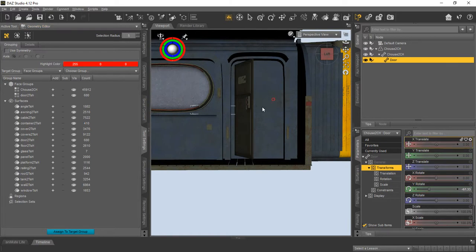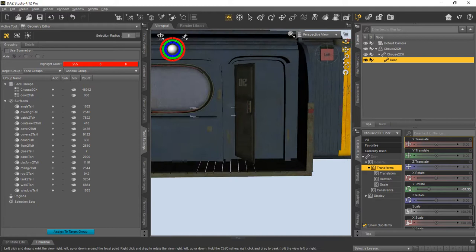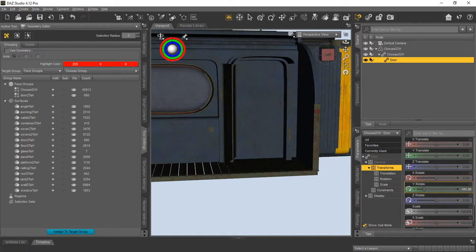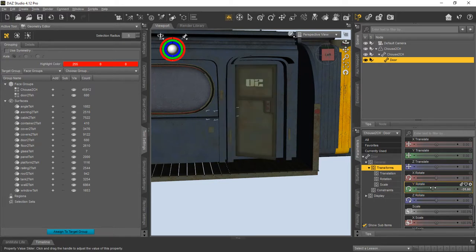Okay. Now that we've created that, all we have to do basically is, we won't want the door to swing all the way open and just all the way into the model like that. So we'll want to put limits on it. So we'll probably limit the door to opening about, let's see, it looks like it's cutting into the model there. So we would just put limits on it by saying, let's say from 0 to minus 90. So we'll go ahead and put this back at 0.